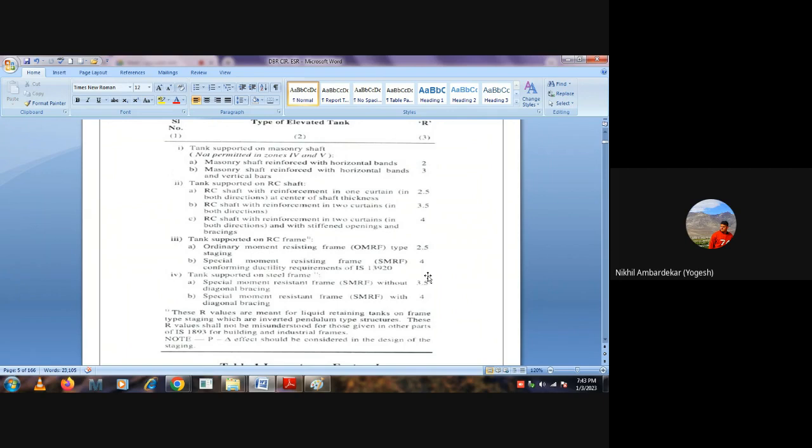Ductile. So obviously yes, we need to provide some flexibility so it can sustain the earthquake force, correct? If it is rigid, what happens? It will be brittle. If it is rigid, it will collapse. Yes, it will attract more force because of the rigidity.